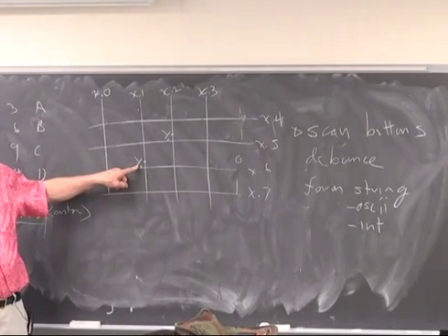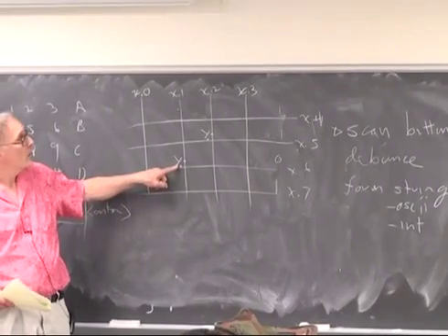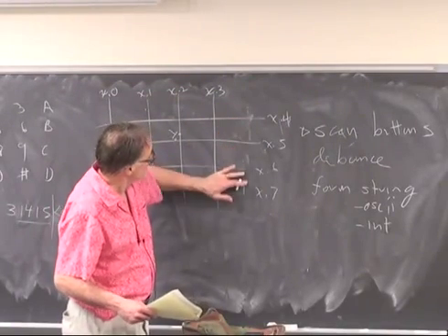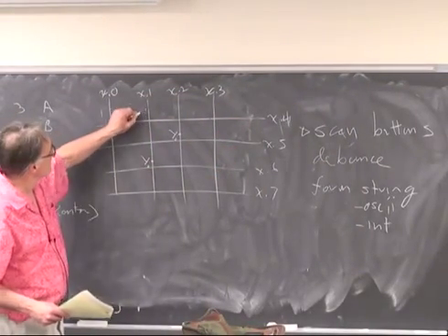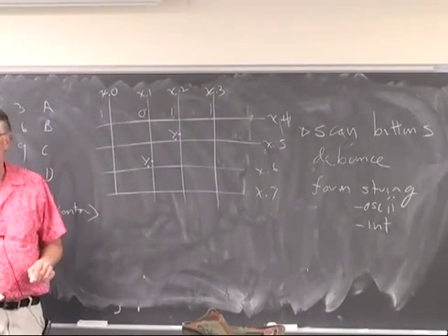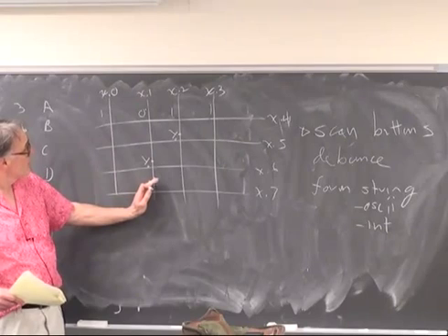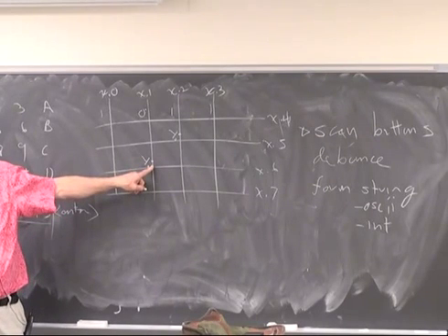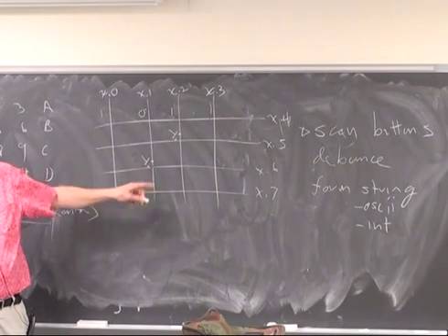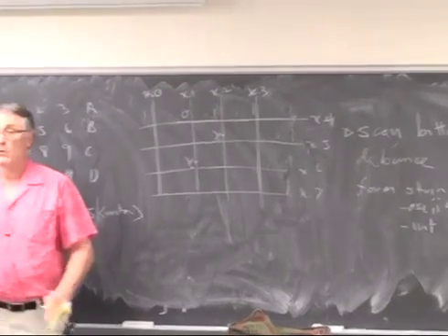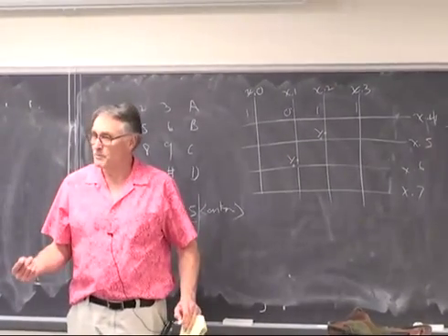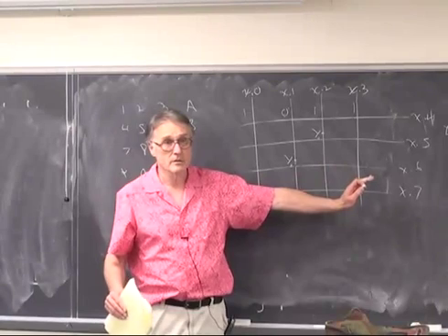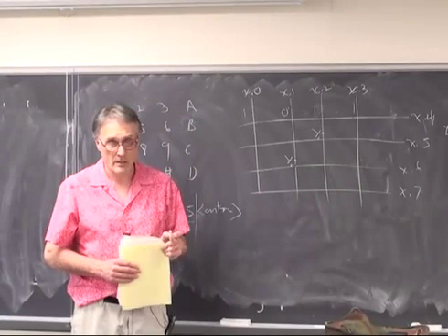Let's say this button has been pushed. Now we flip this around, make these outputs these inputs, and now we have a 1 0 1 1 here. By reading the 0 on this line and the 0 on the previous cycle on this line, we know that that button is pushed. Furthermore, we know that no other button was pushed by accident during the time if there is exactly one 0 in each of the nibbles.